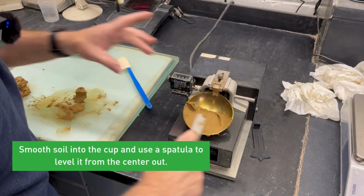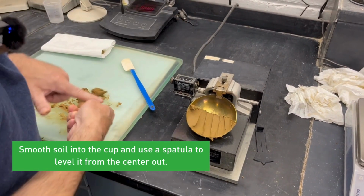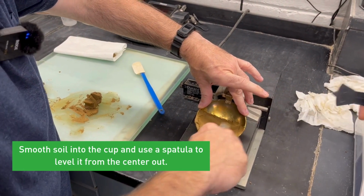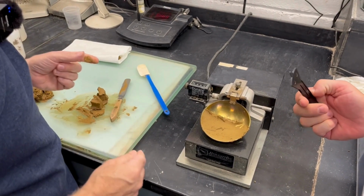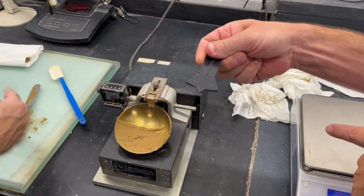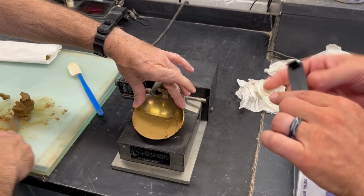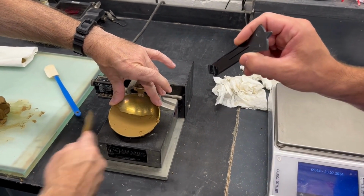And then you're just removing that excess there. Once you're close, you do one more pass to smooth it off. Then we're going to put a groove right down the middle, and the grooving tool is directional. You can see a bit of a taper. The grooving tool serves many purposes. We checked the height earlier, and this is going to be the 1/2-inch gap. We're going to look to close that.